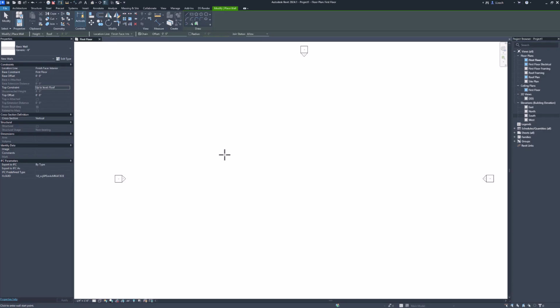So I'm just going to left click, drag a line to the right, about 9'6". I'm going to go straight up. My base cabinet depth is going to be 24 inches, so I want this to be probably 3 feet. I'm going to go to the right. I forgot what that was. 14 feet 1. I think it was 14 feet. 14 space 1. Enter.